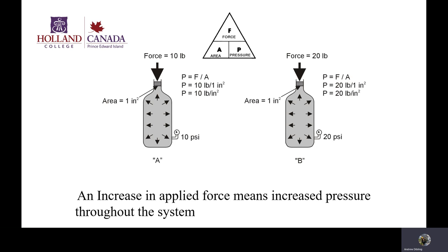Or, if I was dealing with atmospheres, I like to deal with bar. BAR as a unit. You'll probably hear me talking about bar quite a lot. The reason for that is bar is a great measurement when I'm talking about hydraulic systems, because generally hydraulic systems are many, many times above atmospheric pressure. 1 bar, or 1 barometric pressure, is 100 kPa.